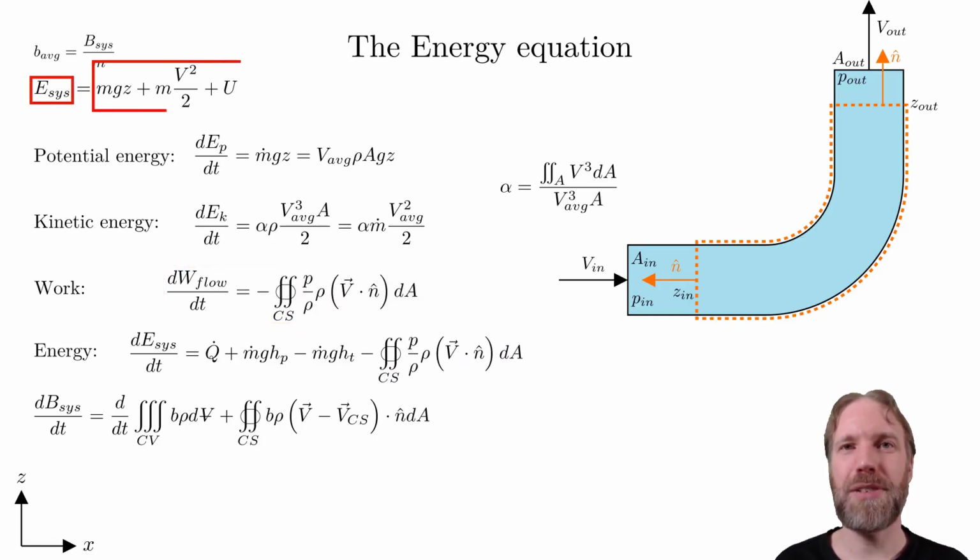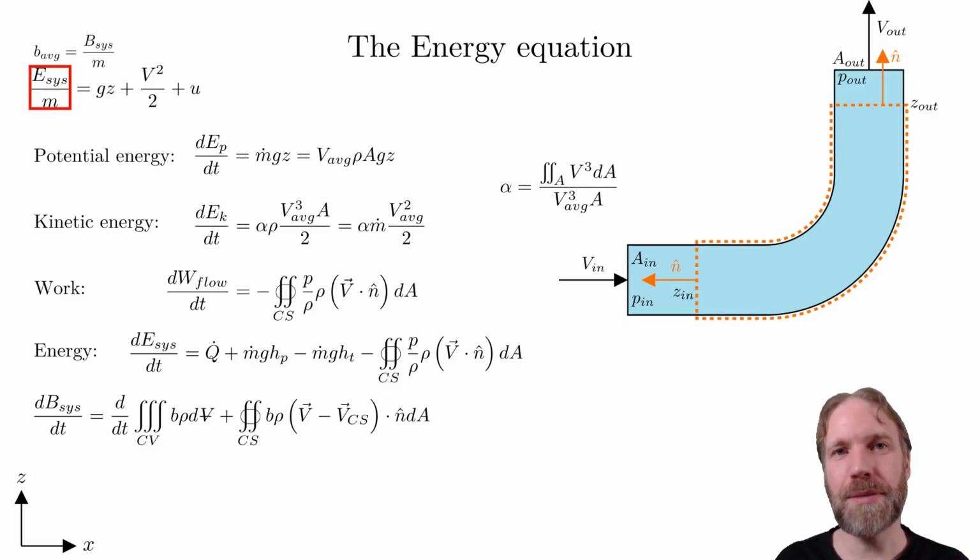As a last step before we are ready to use the Reynolds transport theorem, divide by the mass. The mass cancels. The internal energy per unit mass is the specific internal energy. dE/dt is B for Reynolds transport theorem. To set up the energy expression on the general form would be quite complicated.